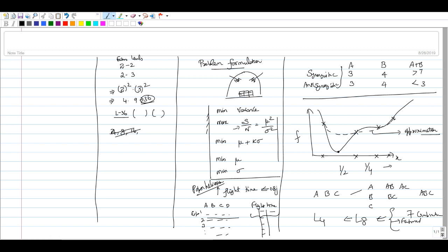There is a balance with respect to the factors in a column sense and between any two columns. That is the biggest advantage of an orthogonal array, because you are not biased. If you compare it with one factor at a time, this orthogonal array gives you this balance. You are not biased against any particular factor. All factors are considered the same number of times.